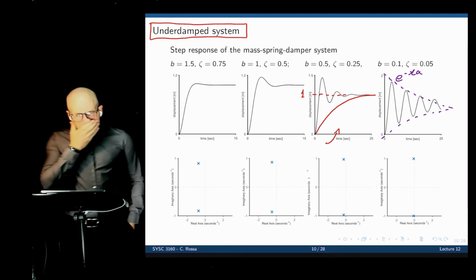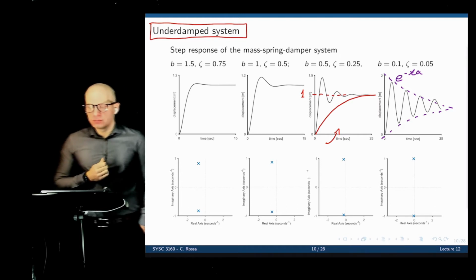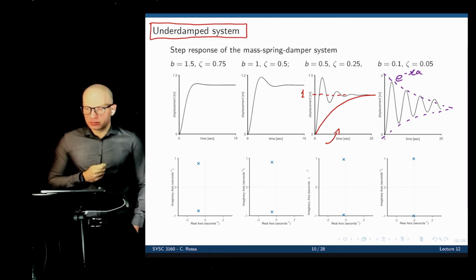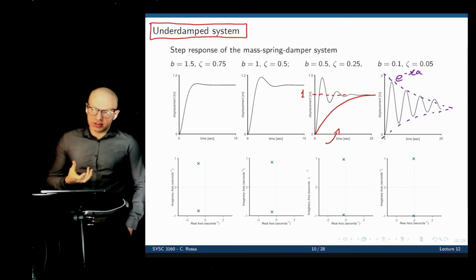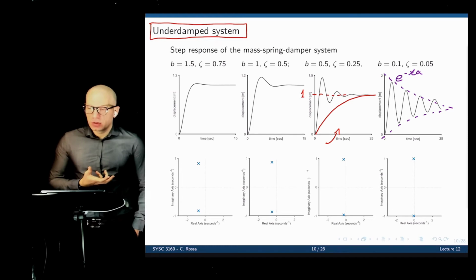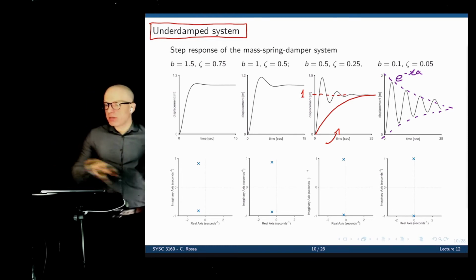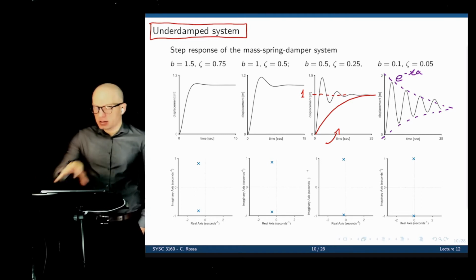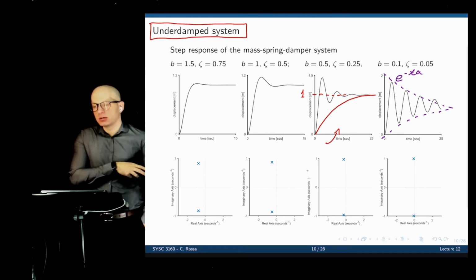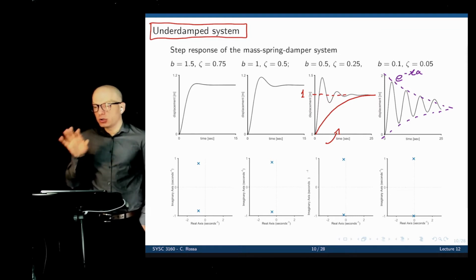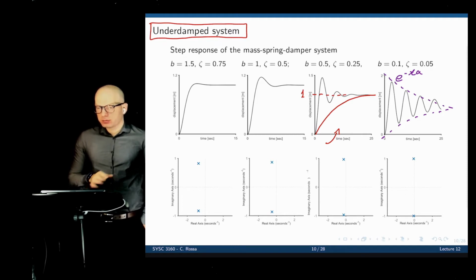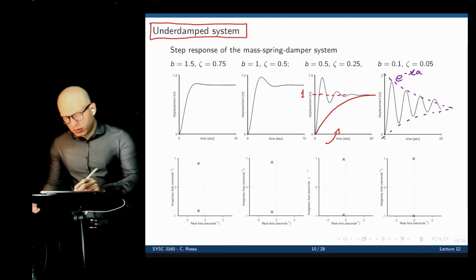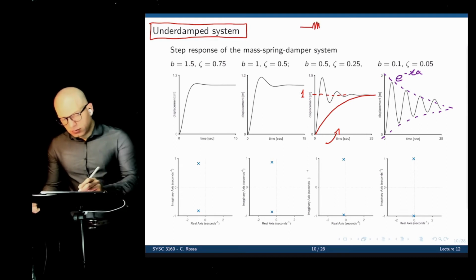Got it. Thank you. I have a question. So you said as it reaches infinity, the function would decay to 0. Does that mean these exponentials, or these graphs, would eventually go back down? No, these graphs are the time response of the system to a step input. The step input always remains, but the transients that are generated by the allocation of poles eventually disappear. Only the transient disappears. The steady state is not necessarily 0. Oh, so it basically just stops increasing at the level of the step function.